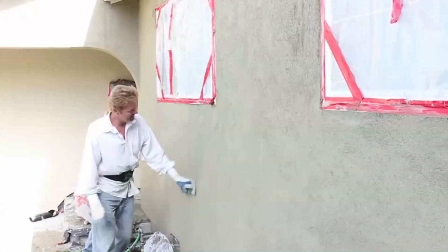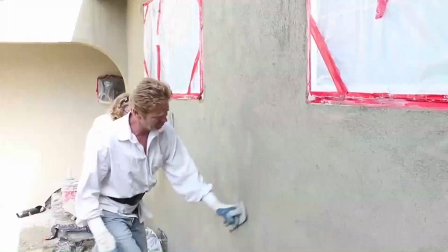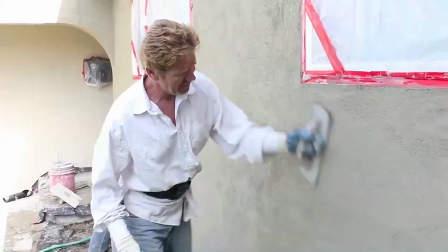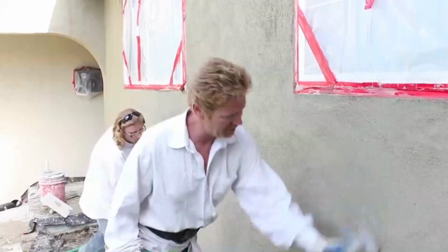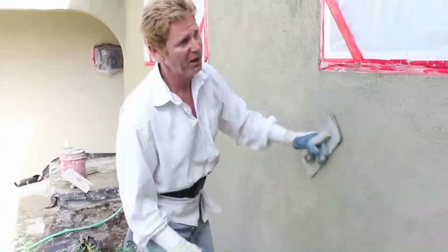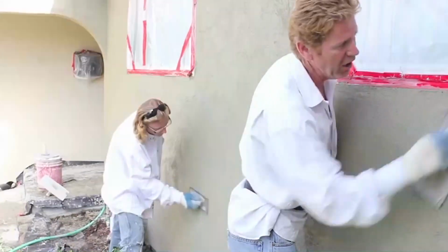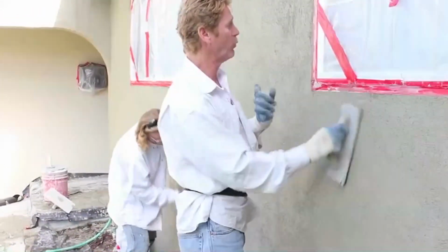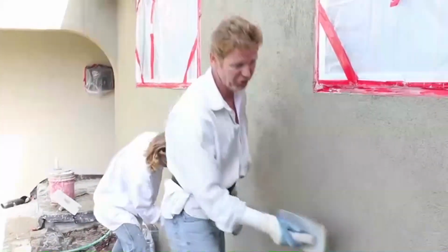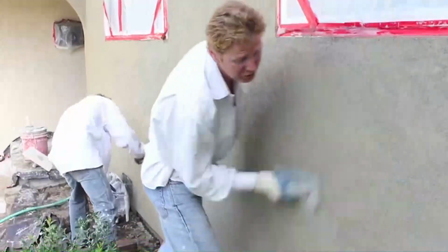All right, guys, we are all hungry. We've got food over here waiting for us, but this particular product doesn't wait for anybody. This is rapid set, man. It doesn't wait for anybody. So we're pushing in hard, going back, going over everything. In about 15 more minutes, we're gonna have it. Then we're all gonna take lunch. You really have to use a lot of elbow grease with this and hit it while it's real hard. If I wait another half hour, I won't have enough muscle to push it in. So when you're using this particular product, you need a certification and you better know what you're doing.